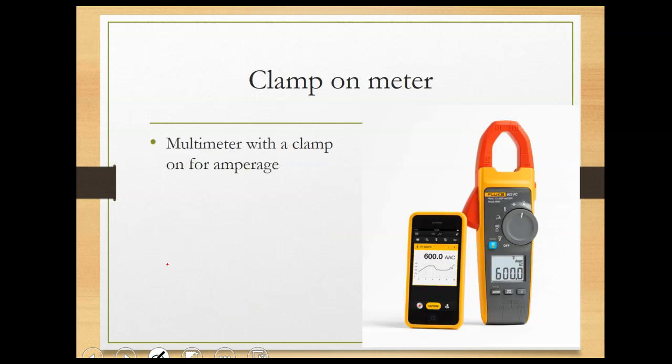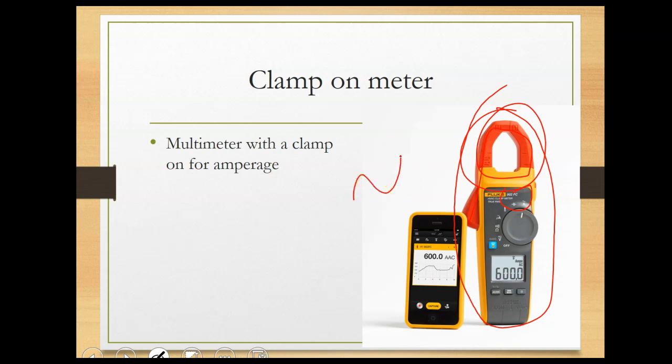And the second thing is the clamp-on meter. This clamp-on meter by Fluke is the 902 model, and it can measure amperage because it has the clamp-on ability here. If you look here, you have to set it on amperage. It has amperage AC. This squiggly line you see over here is AC. This part is for the capacitors, which is very nice to have because you need to do that for ACs and for some motors. And here you see the temperature.